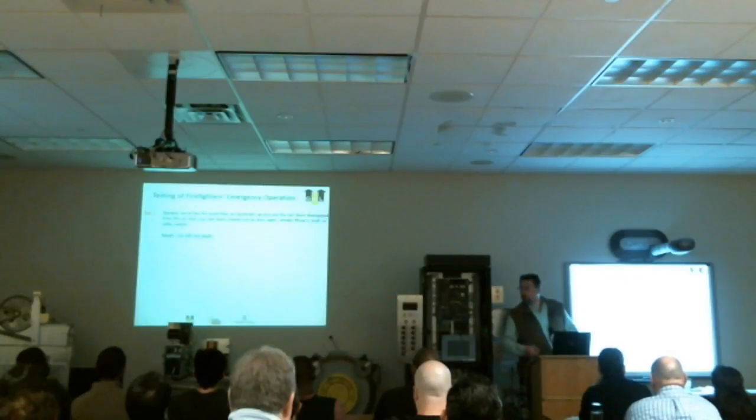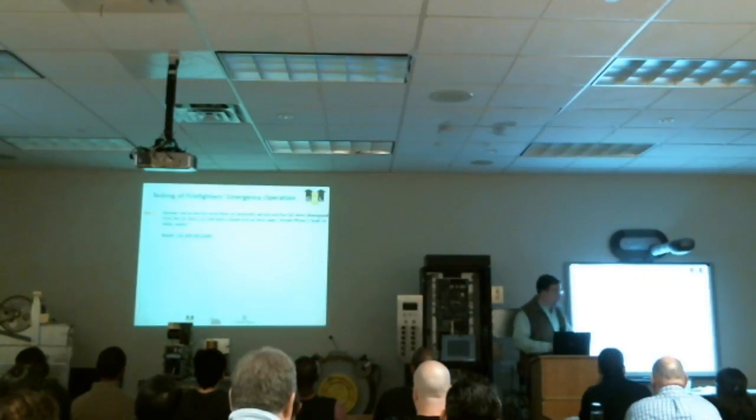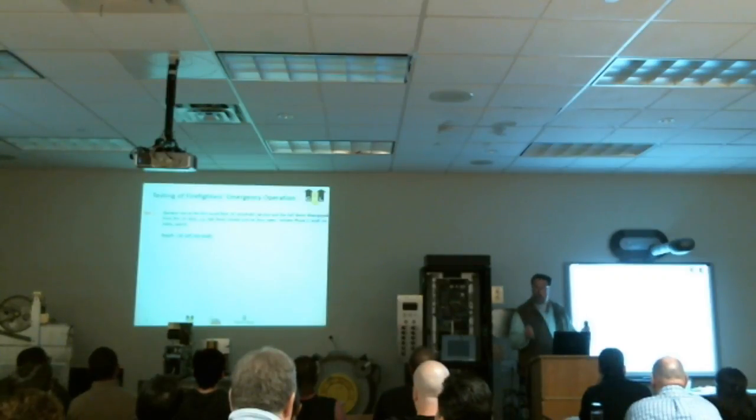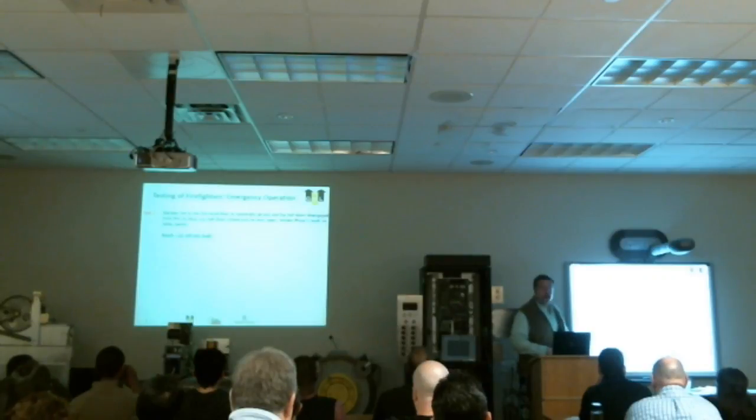Car will not recall. The car should stay shut down, out of service. So it's not going to be able to recall the elevator. If the car is on automatic, happens to have a fault condition, and the fireman initiates the phase 1 recall, the elevator will not recall.